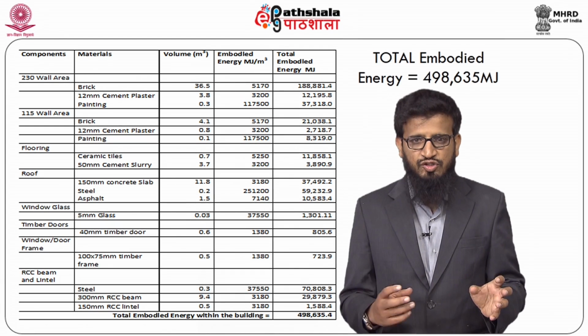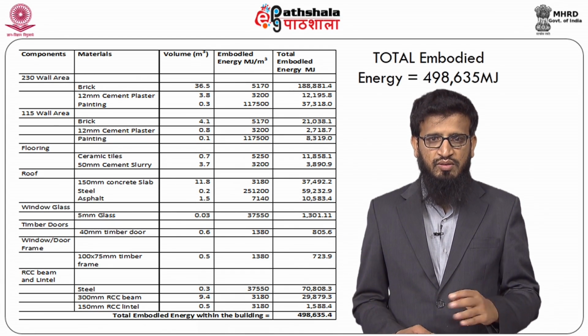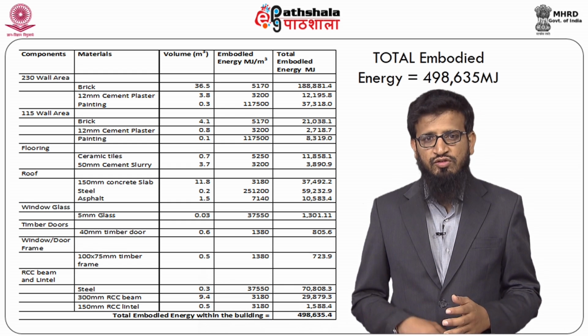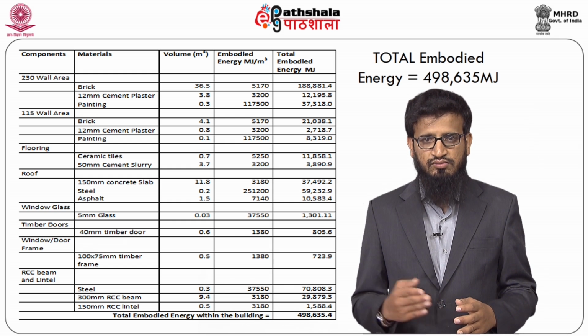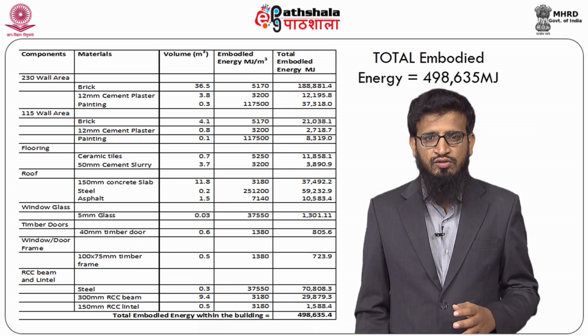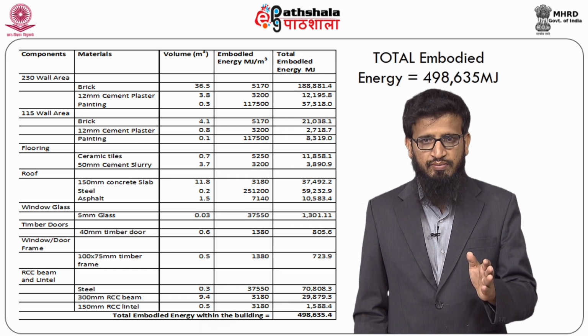The reason we are doing this is to understand the different methods of how you can compare, so that you are not caught out when somebody gives you megajoules per meter cube and you don't know how to calculate it, or somebody gives you megajoules per kg and you don't know how to calculate it. In the megajoules per kg calculation we use the mass. In this one we will not use mass, we will use just the volume. So what we go about is pretty much the same.